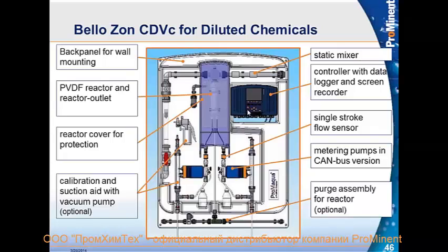The bypass water is regulated by the PLC, so if the water slows down, the whole process slows down. If the water increases, then the pumps increase, and everything is kept in a very stoichiometric equation here. There's a static mixer that helps also to mix the chlorine dioxide solution with the water and then out into your process. So very simple.